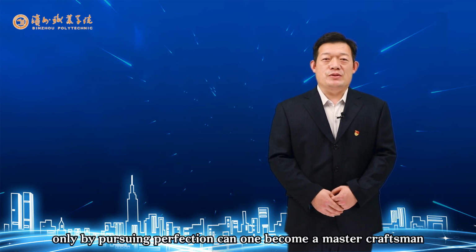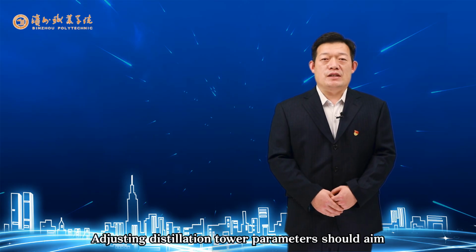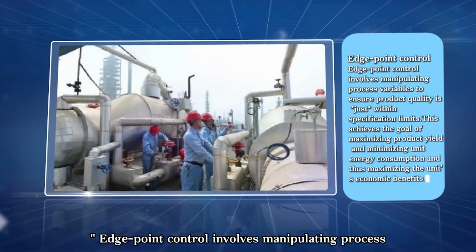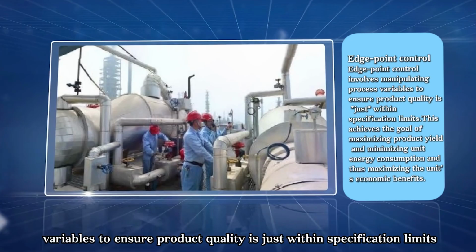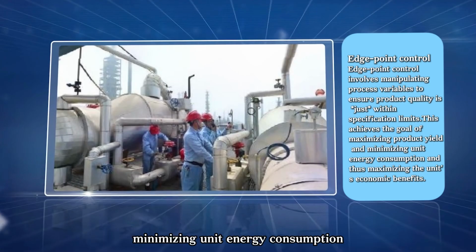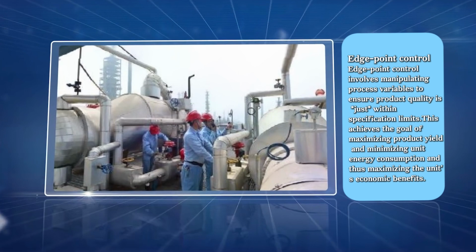Classmates, only by pursuing perfection can one become a master craftsman. Adjusting distillation tower parameters should aim for edge point control. Edge point control involves manipulating process variables to ensure product quality is just within specification limits. This achieves the goal of maximizing product yield, minimizing unit energy consumption, and thus maximizing the unit's economic benefits. This is crucial for side stream product quality control.